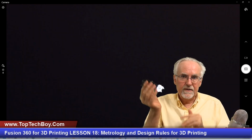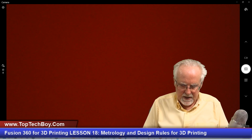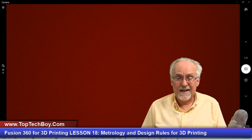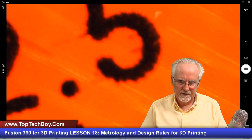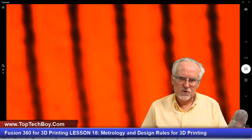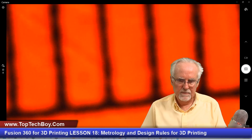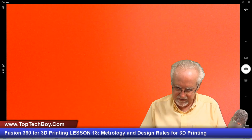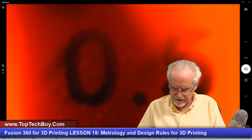The other thing that I really like about this little microscope is it comes with a little measurement gauge. And let me show you what is really, really super neat. That little gap that I just made would be very hard to get the calipers on and do any type of metrology on. But what I want you to see is this has a little clear ruler, and each one of these little things is 1 millimeter. So you can see that I can put this clear ruler over, and let's say that I come over here to here.